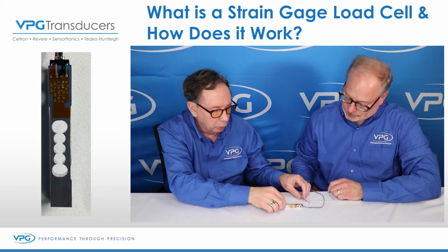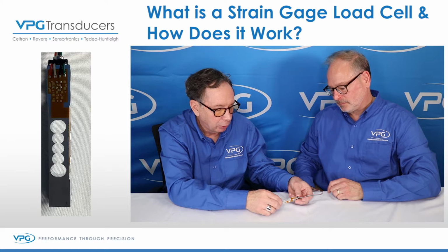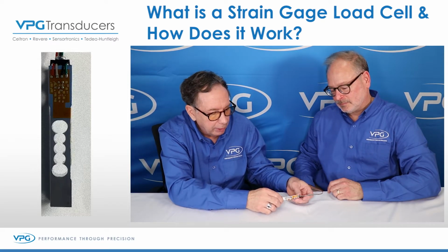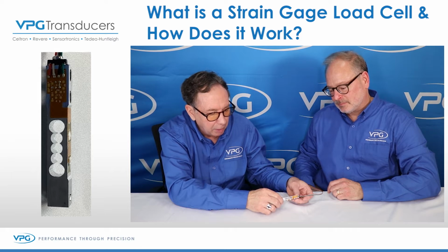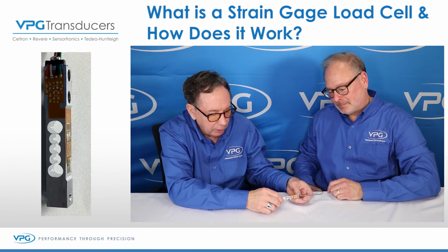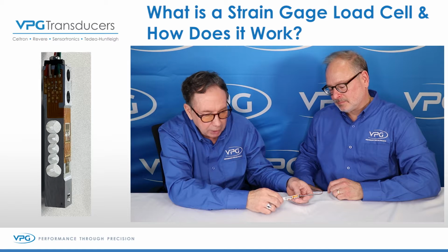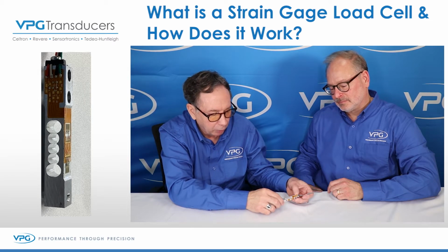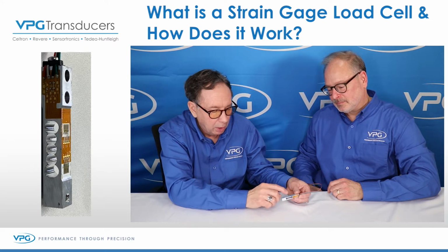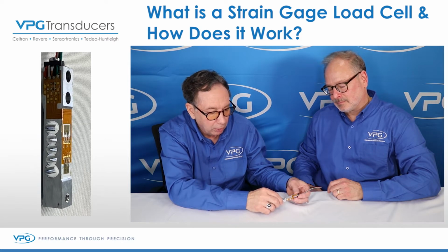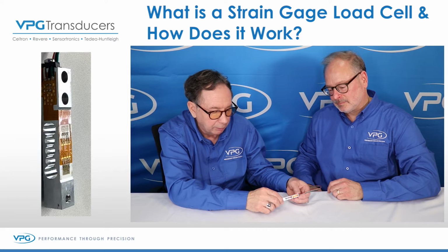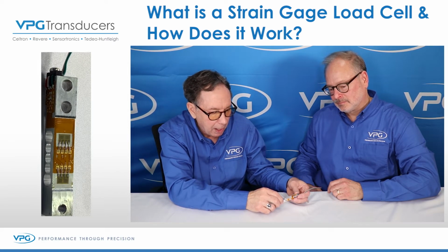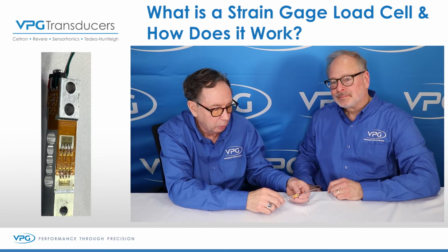Sure. Load cells are really unique in that they are truly an electromechanical device. And what I mean by that is the load cell itself is really a mechanical beam. The mechanical beam is going to deflect a given amount under a given load. And it's all calculated by the amount of deflection material that's left, as well as the mechanics and materials of the aluminum or the steel, alloy steel that we use in the construction of it. So we need to find somehow a way to convert that mechanical deflection into a usable signal.